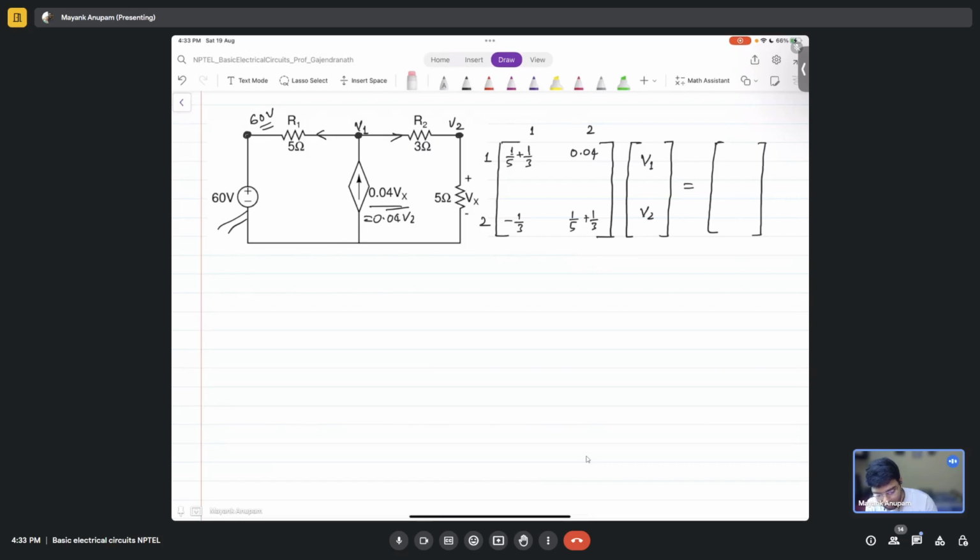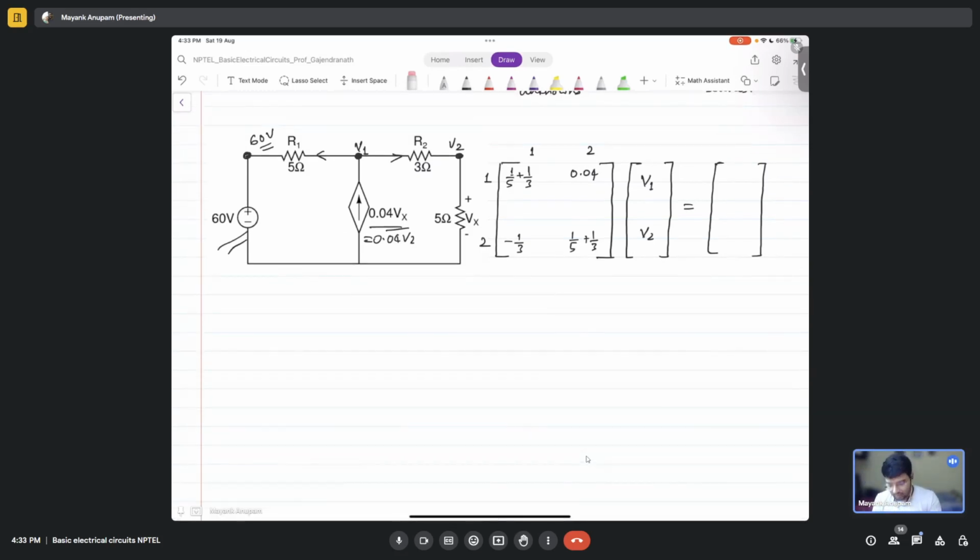So what I'm trying to say is, you know how circuits are solved in the computer, in the simulator. Circuits in the simulator are all stored in terms of a graph. By graph I mean you have a whole bunch of nodes, and you have the elements connected between those nodes. You have branches for them. And the computer starts to formulate a matrix of those nodes, something similar to this.